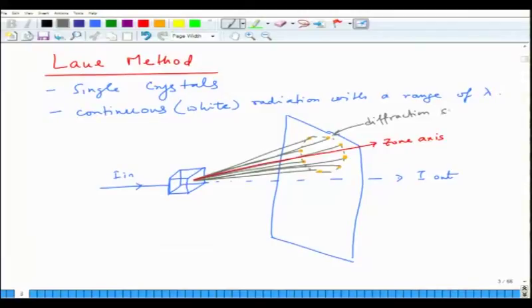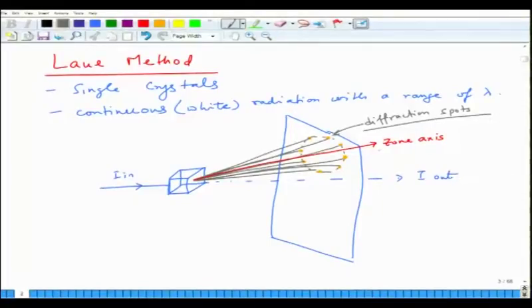Diffraction spots. So then we need to carry out an analysis, because if these are the spots from the diffracting planes which have a common zone axis, then we know Weiss zone law, right? Weiss zone law says that for a zone axis, the dot product of HKL and UVW must be equal to 0. So if this was UVW and these planes had, let us say, H1